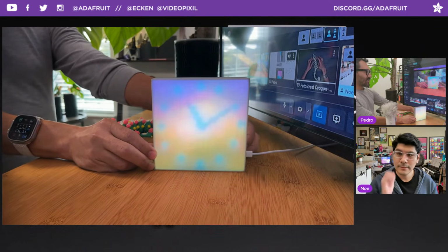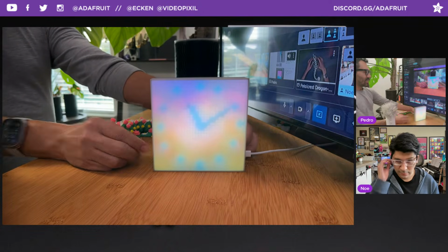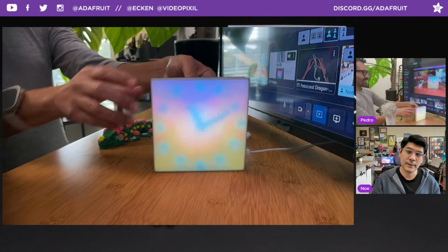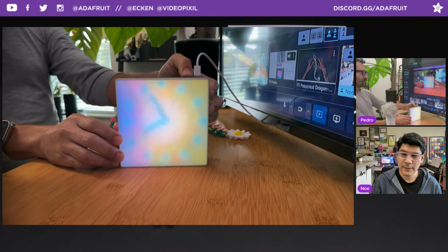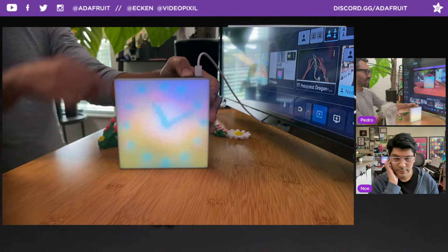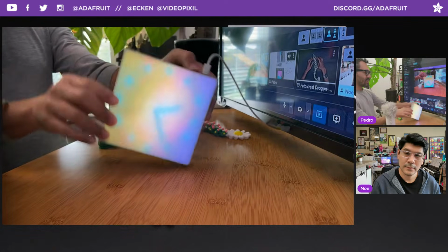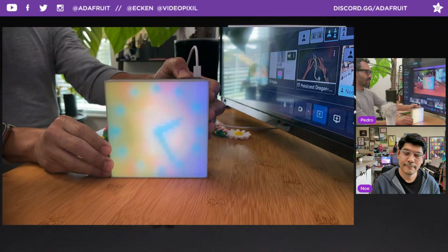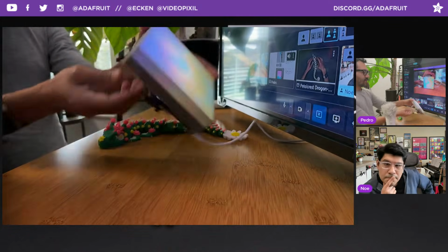And then as I'm finishing up the project, going through the guide, I failed to remember that the Matrix Portal S3 has a LIS3DH in there. It does. So I could have had the accelerometer sense what angle it's at, but we have it on there manually. So if you hold down the up button, you can change the orientation to have it be hung up, or if you want to have it at a different angle, it'll accommodate that. So you can manually set the screen rotation if you want to have it on a desk, or if you want to have it mounted on a wall.